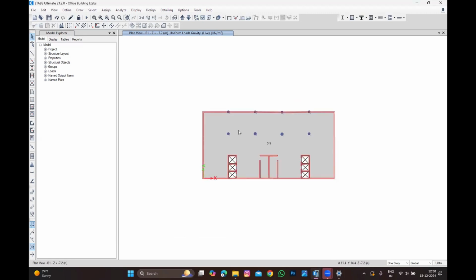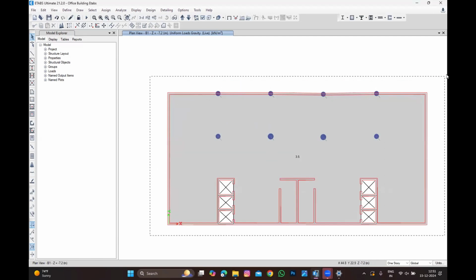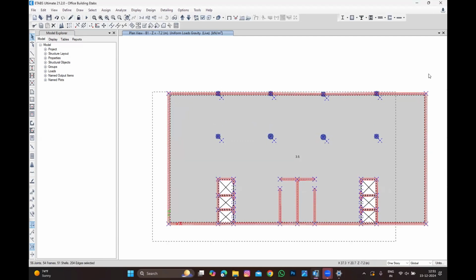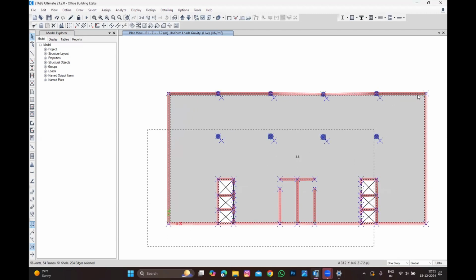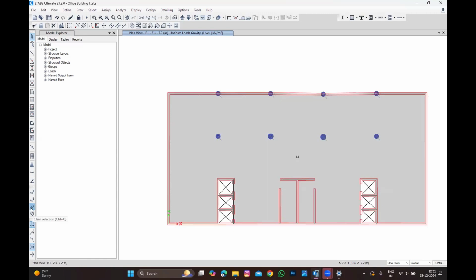Now what I'm going to do, I will just select this and remove this line. See, I'll tell you here. I selected here, right? To unselect, don't do undo, Control Z, because if you do Control Z, everything will go away. Can you see my cursor on the left side? There is an option called CLR. Click CLR, the selection will go away.